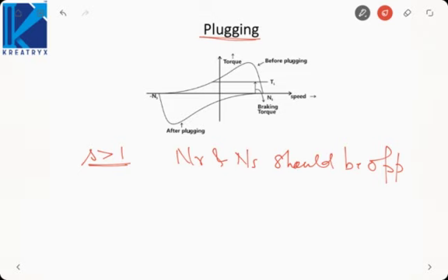But we can reverse the direction of rotation of the stator magnetic field. To reverse the direction of the stator magnetic field, we have to change the phase sequence. If the phase sequence is ABC, I change it to ACB, and the rotation direction of the stator magnetic field reverses, which can be done by interchanging the two terminals B and C.